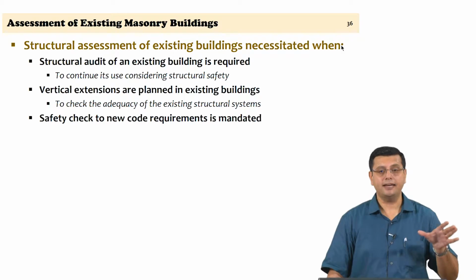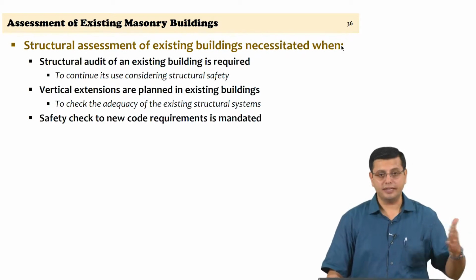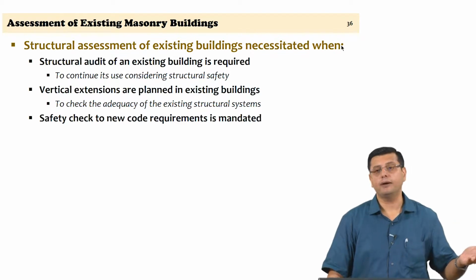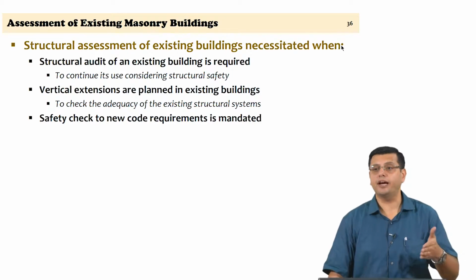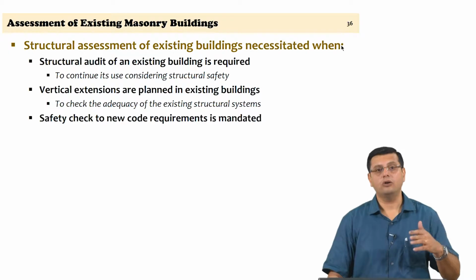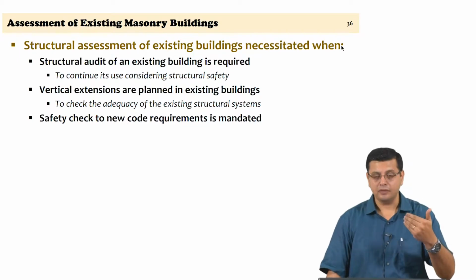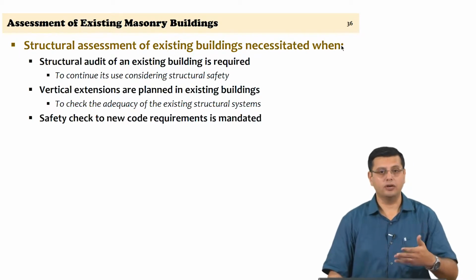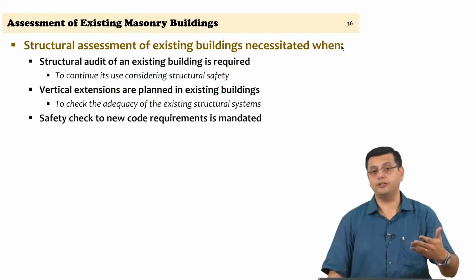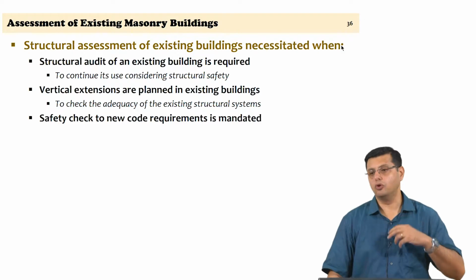So, you are looking at existing buildings which have been designed in the pre 2002 regime, where seismic design might not have been addressed at all. So, these are all gravity frames. Therefore, these buildings would actually fall short of requirements of earthquake safety. Now, that is true for public buildings and that is true for private buildings. So, it starts becoming the prerogative of the public authorities or the private owners to want to ensure compliance of the existing facility to the new code requirement.